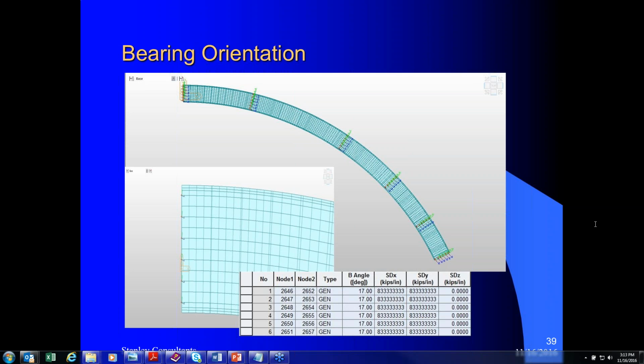So that also needs to be added as a centrifugal force in addition to the truck wheel reactions, which are the normal distribution of the vertical forces. But in addition to that, you also need to input the lateral force.